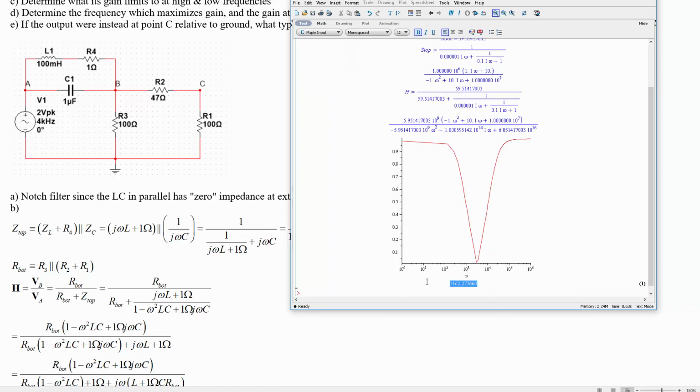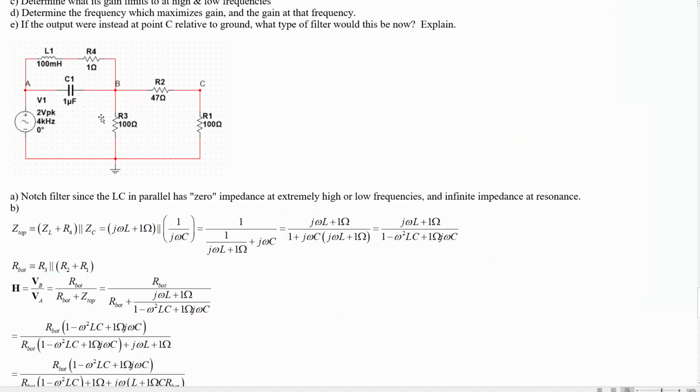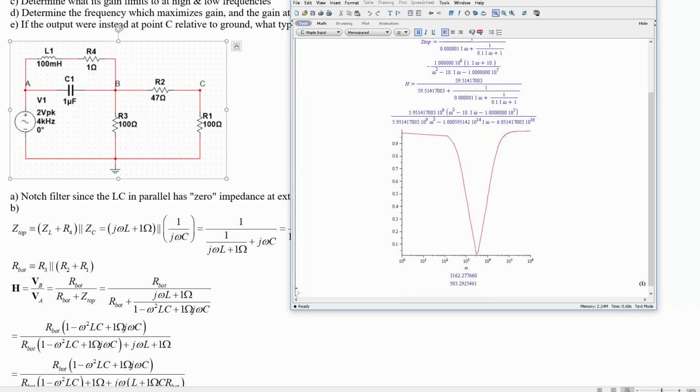Yeah, so 3,200 is what we had. I mean, that's not a new thing. This is actually the same capacitor and inductor value that we were using in the last problem, and that's because these are the ones that we've got in the lab. So the 3,200 is what you'd expect for the omega, and you may remember that the cyclical frequency that corresponds to is about 503, I think. So this is this thing divided by 2 times 3.14159, and we've got 503 hertz that this corresponds to.